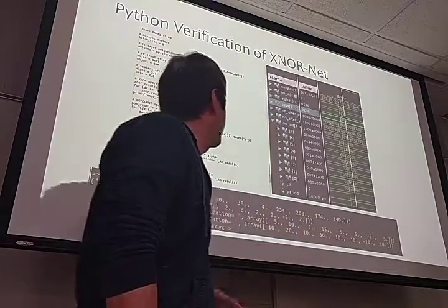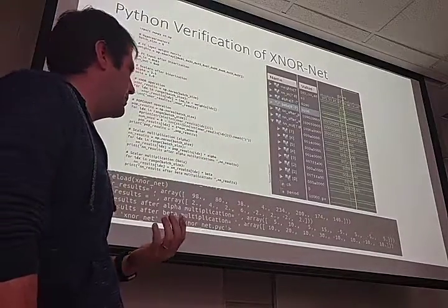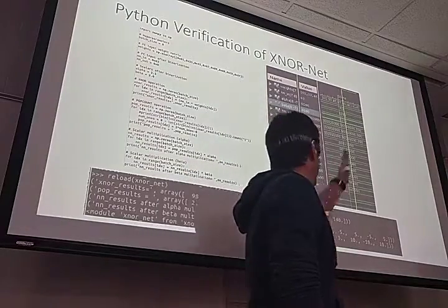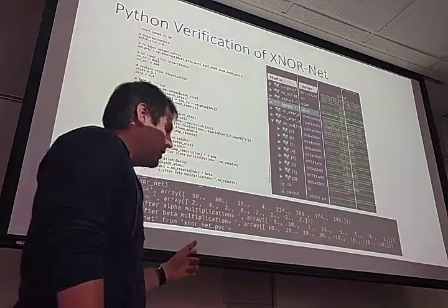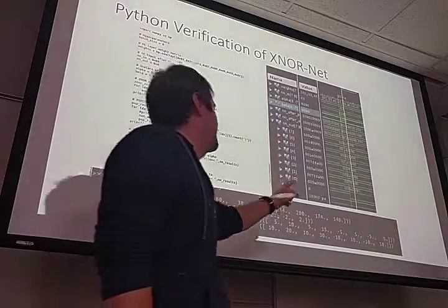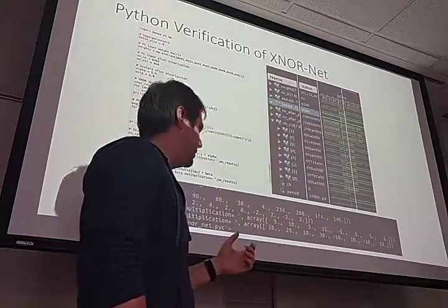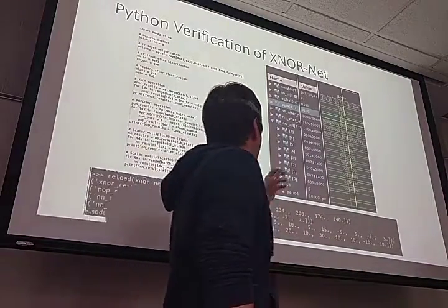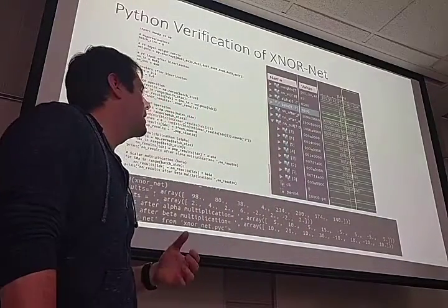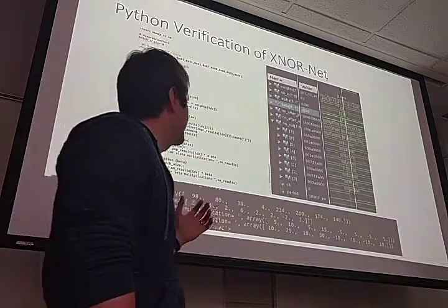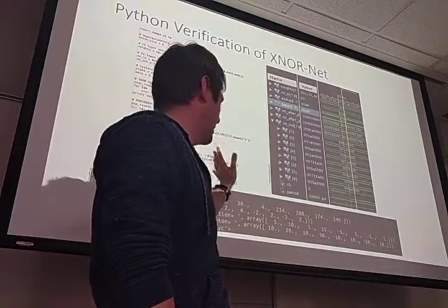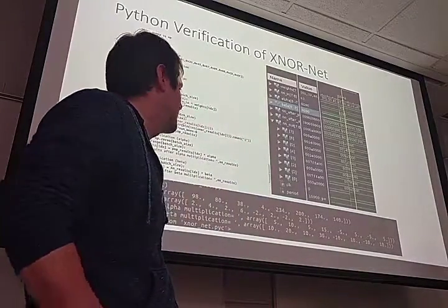So then you can compare these numbers, and you can look at the 10 and 20, for instance, with the hardware simulation outputs. That compares to these two up here. You can see this is a 32-bit fixed point notation. We have 16 bits representing the integer, and 16 bits representing the fraction. So 0, 0, 0, A, 0, 0, 0, 0 just represents 10.0, which matches up with our results. Similarly, we have 0, 0, 1, 4, 0, 0, so that's 4 plus 16, which is 20, which is what we see here. Then you can go along the line, and we can see that we match up perfectly with our simulation results.